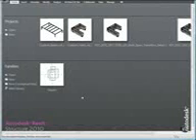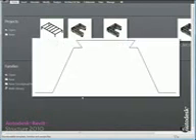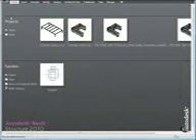In this lesson, we will create a custom non-composite metal deck family by adding a dovetail rib to the deck profile. Click the menu browser and select Open. And from the Training Files Imperial folder, open the file Form Deck Non-Composite.